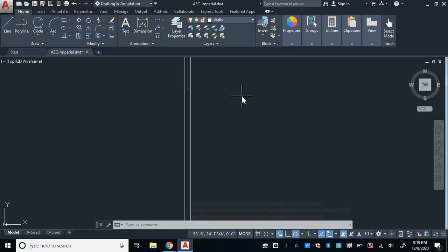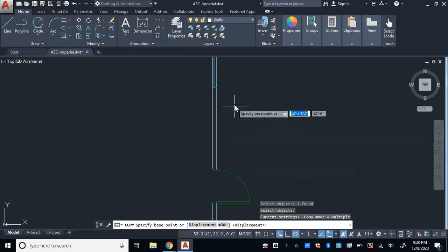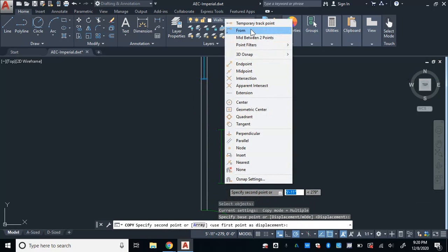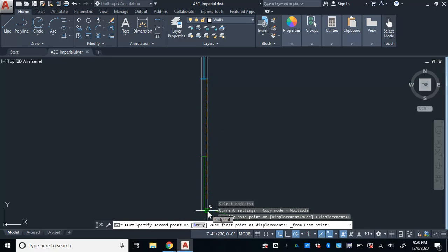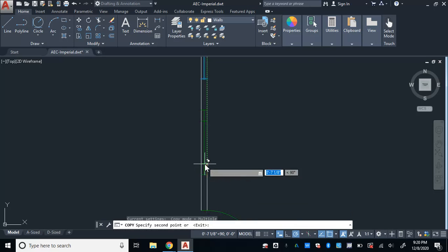We're going to, no. I don't know. Looking at the picture, it doesn't really specifically say. And looking at what it states, I'm not quite sure. So I'm just going to use my best judgment for this. I'm just going to place it 2 foot from this side in. All right. So we'll make a copy. Hit enter. This time I'm going to pick this corner of the wall and I'll control right click, do from. I then click the point I want to reference my measurement from and then go up to apostrophe enter.